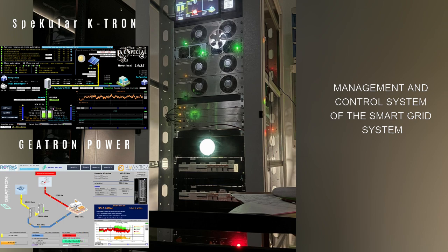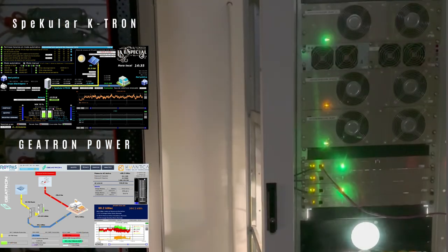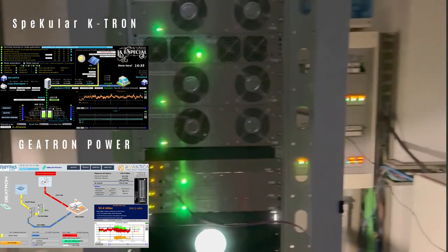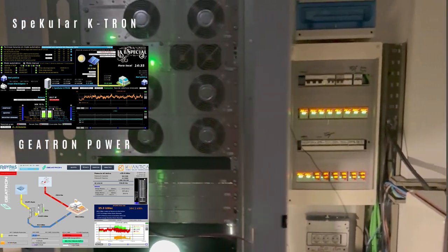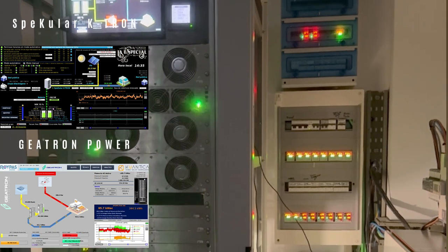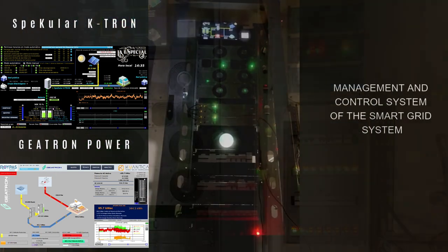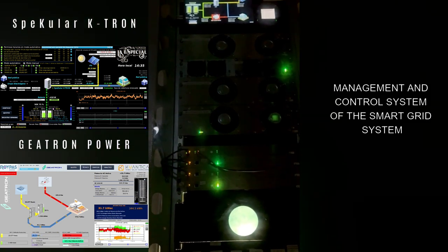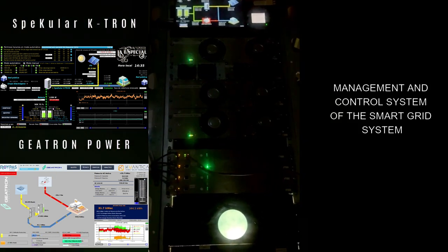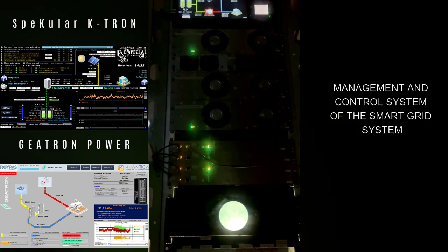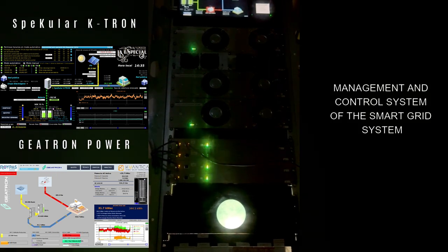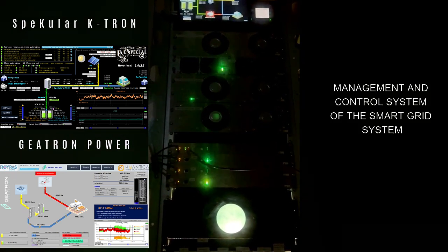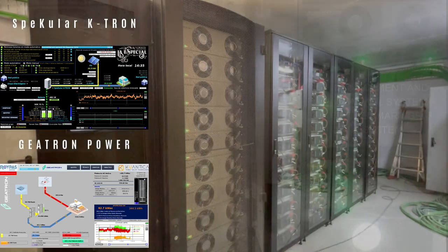Operating in parallel mode with the grid, parameterization of charge and discharge management from and to the electrical grid based on pre-established schedules and power levels, and based on battery charge states. Operating in parallel mode with the grid, management of the power supply required to cover excess power consumption over the contracted power from the electrical grid. Operating in parallel mode with the grid, continuous management of reactive power supply without penalizing active power generation.